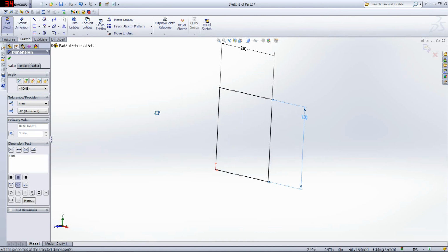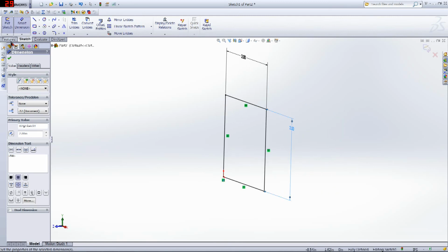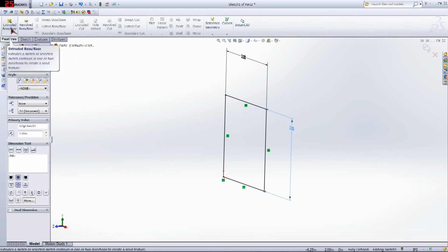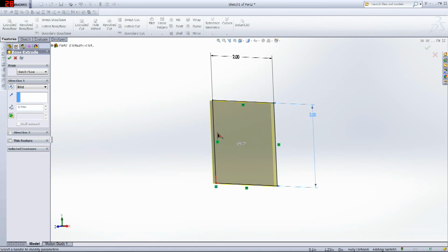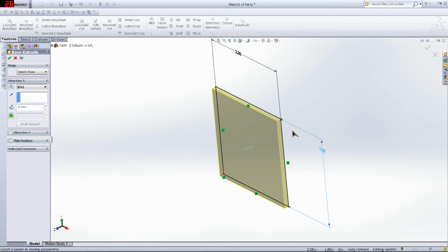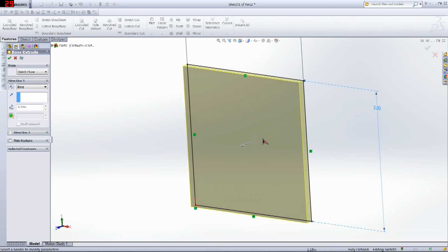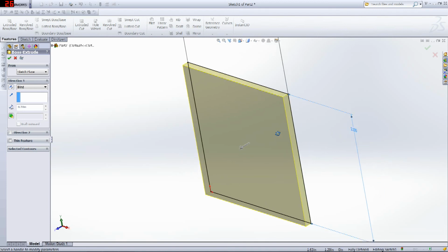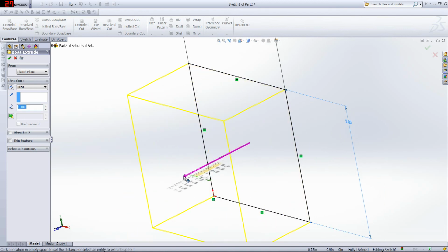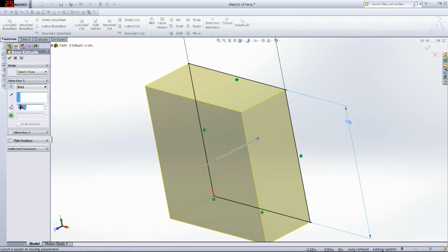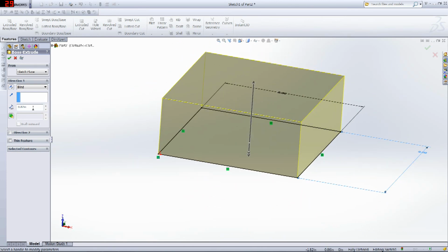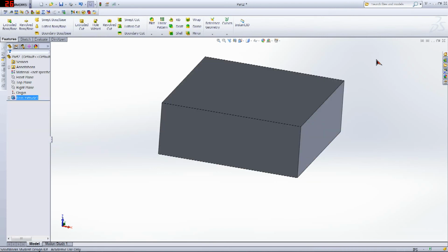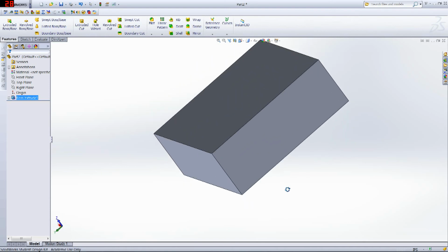Check that out, rotate in 3D, and now we want to change it to 3D. So here you go to features because you're changing this 2D object to a 3D object, and here's Extruded Boss Base. This basically allows you to create material using your sketch. See, this is the preview page. Here it shows it in kind of yellowish, showing basically what direction it's going to be headed, or what it's going to look like, sort of. And here you can edit those exact dimensions to exactly how far you want it out to be. In this case, it will be 0.75. Check mark there. And now you have your first box.